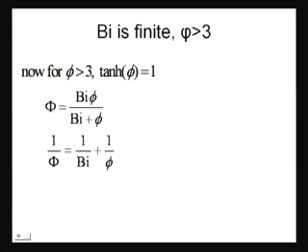What does this suggest? Physically, what does this suggest? We had done something like this, not exactly the same, but something like this before. Which two resistances? One would be mass transfer. Two resistances are in series, but look at this carefully. They are not exactly in series. Okay, it is not the linear sum. This you can signify as a mass transfer resistance. Then this one looks like the diffusion resistance, but square root of that, because the actual diffusion resistance would be given by 1 over phi square. So it's a summation of the resistances, but not a linear sum of the resistances.